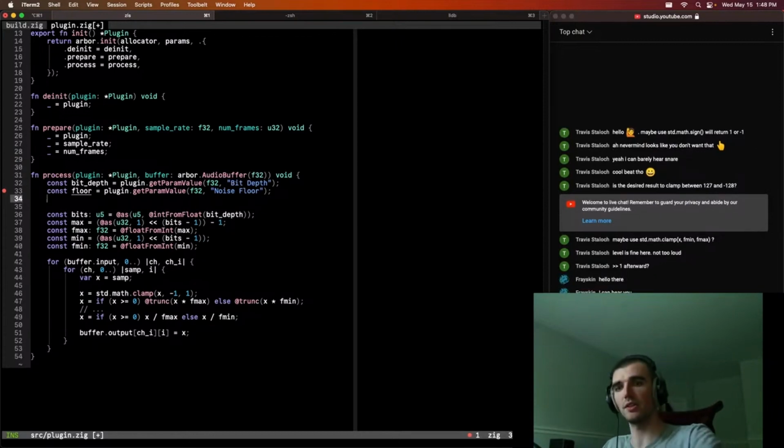When you just add noise to that bit depth noise floor, so minus 96 dB noise at 16 bits or whatever, yeah, I guess that would be a more accurate way of doing it, if you want to explicitly specify what the noise floor is at. I guess what I'm more interested in is what happens if you underfeed the bit crushing process.